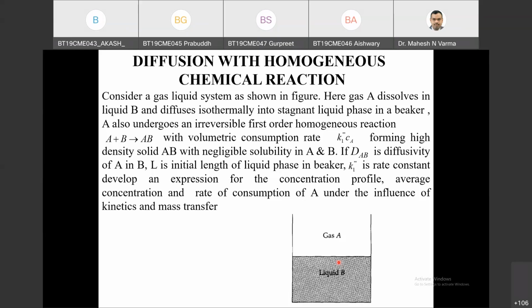So if I use one boundary condition of flux, that intermediate constant will be evaluated, and then we will get a first order differential equation with respect to concentration. So one flux condition and one concentration condition is also enough. But as I am getting only a first order differential equation in flux, the problem cannot be solved even if two flux boundary conditions are given. Everybody should make sure of this.